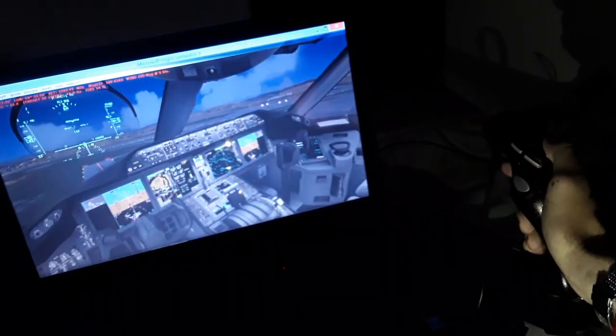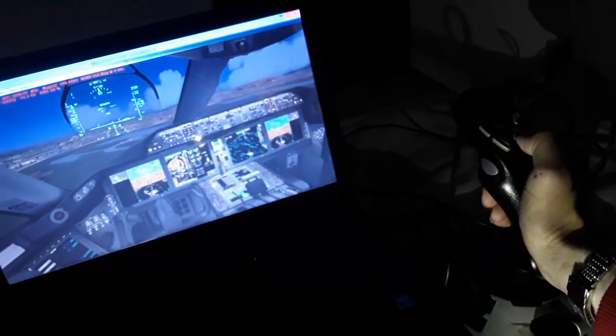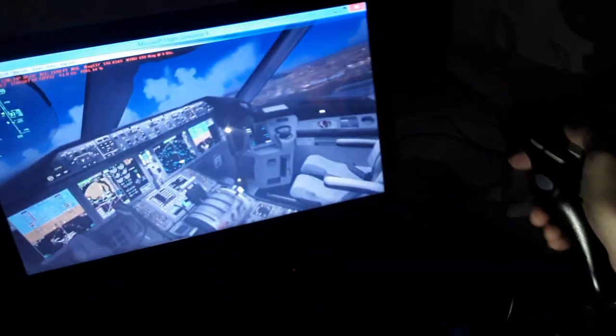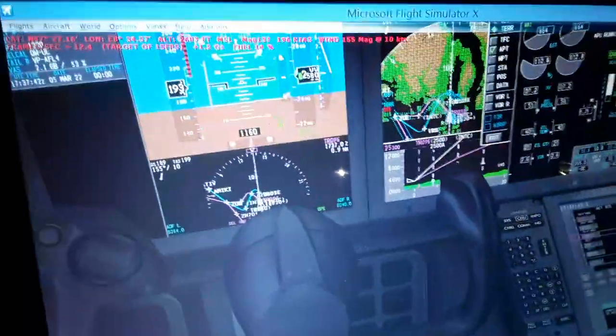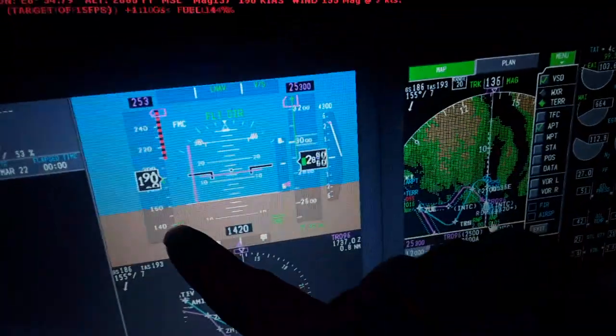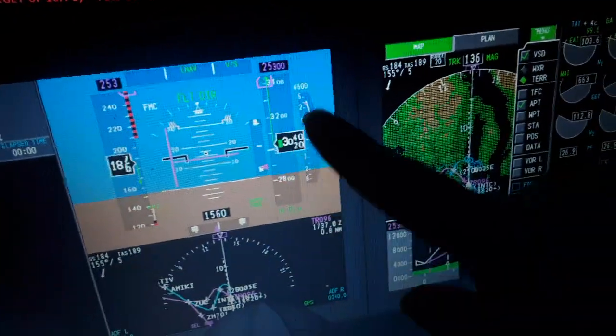of the aircraft. We can leave the flight controls off if we need, there is no problem. It keeps flying by itself, it's a fly-by-wire aircraft. We don't need the autopilot or flight controls by itself, as you can see, keeps climbing. So this is the controls, all what you need to see over here. You can see the airspeed 190 knots, the stall speed, the wind direction and speed here, the rate of climb.